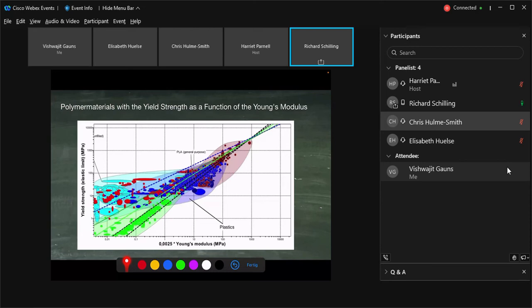And here you see that for the normal exponential answer, you will have almost all of the foam materials. And for the elastomeric materials, which you find here, you have 0.9, 0.8, 0.7, 0.6 as the power which you have to describe the time behavior, the time response of these rubber materials.